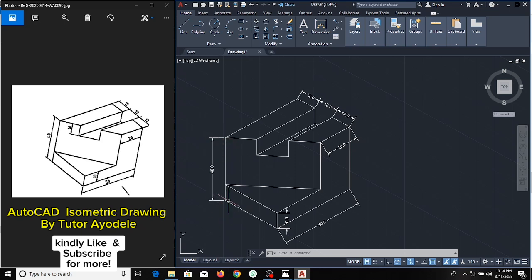We have this in 150 degree. Like if this was a straight line, going this way, if we start our angle going like this, this would be in 150 degree to that. So we need to set this to 150 degree, set this to 30 degree, this to 90 degree, this dimension to 90 degree, and this one to 30 degree.